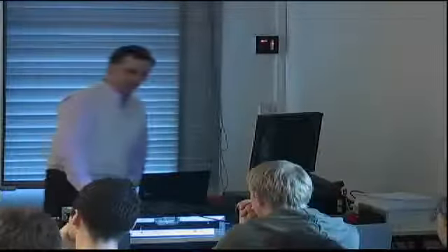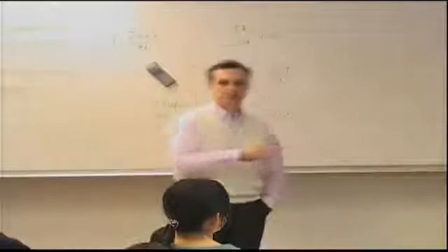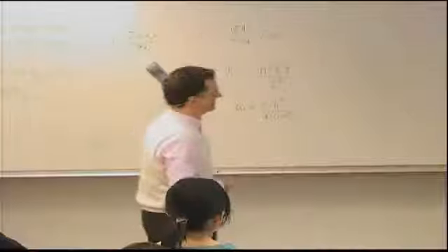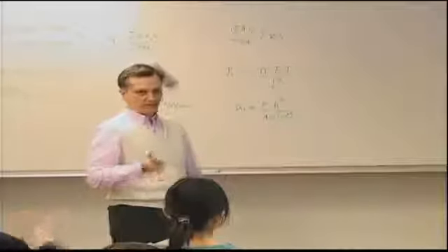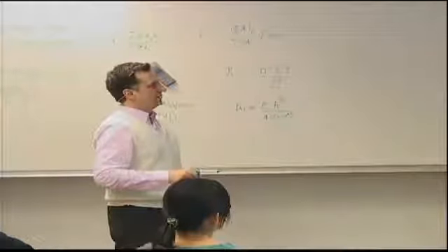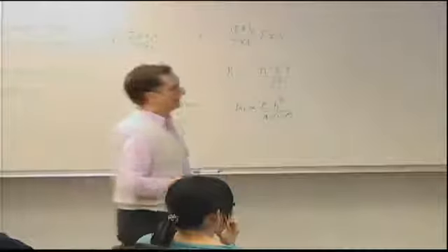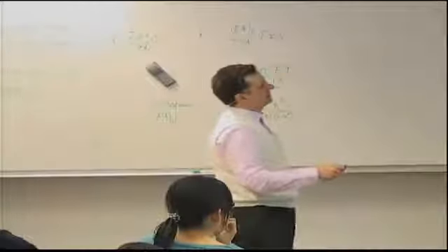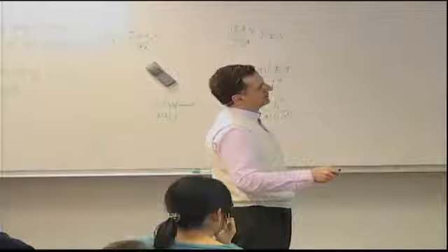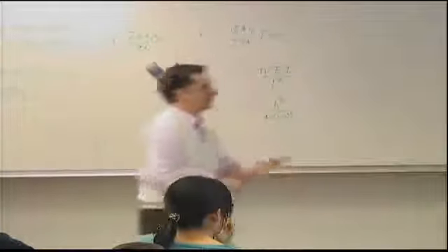Let's talk about what happens in a structure with fasteners and load being transferred from one member to another. Now, this is not a course about joints. There's a special course that does this, but it's good to put it in perspective. Suppose I have the blue laminate and the light blue laminate, both under load P, and I have 3 fasteners. In fact, when you test it, it looks something like this. You will see that the fasteners tilt like crazy and they start digging into the structure, into the composite.